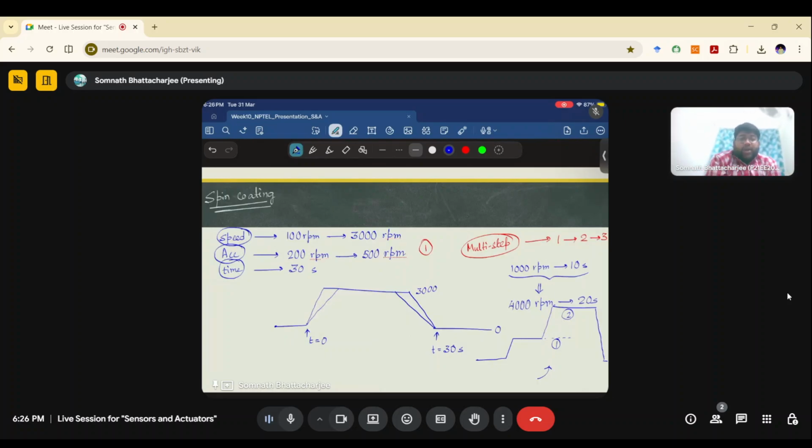For several different kinds of materials we may have an annealing stage. If we need a very gradual annealing, we can have 20 or 25 degrees centigrade and give it, let's say, 2 days or something like that. So it is gradual. And for some cases, if we need rapid annealing, we can give it, let's say, 150 degrees for only 10 minutes or something like that.